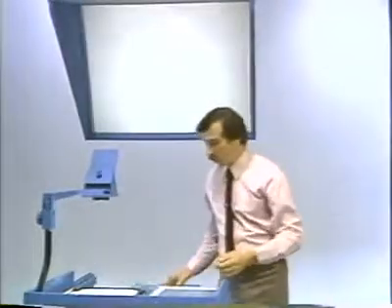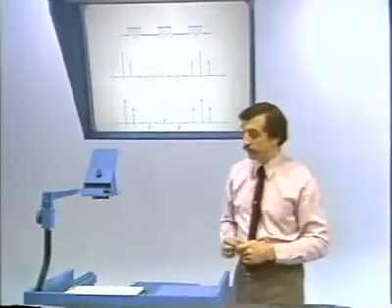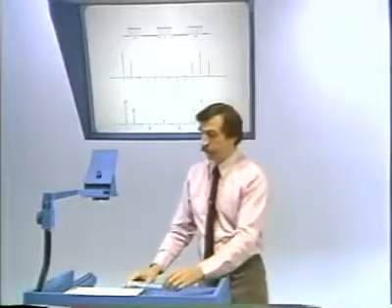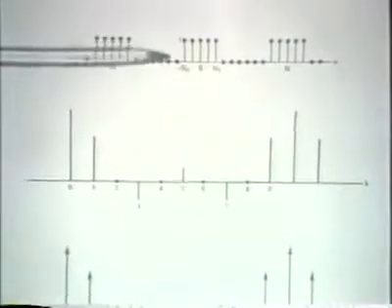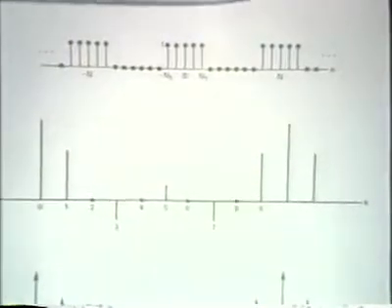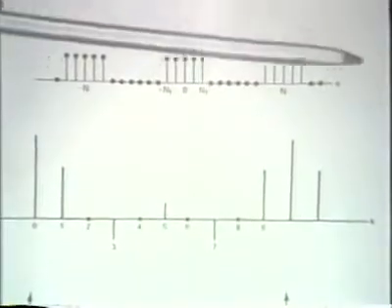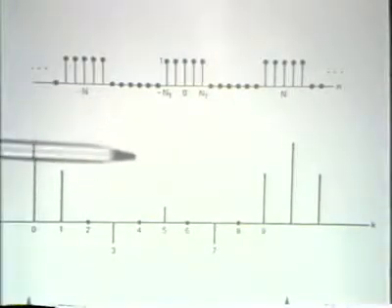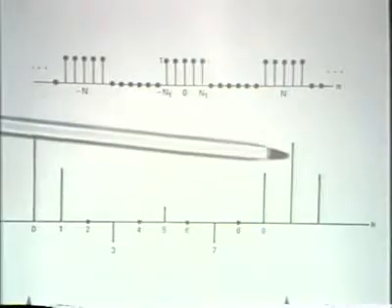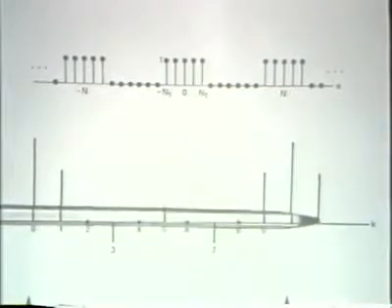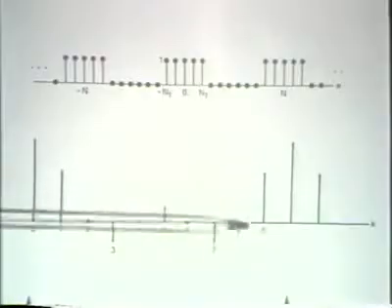So once more, returning to our example, the square wave example that we've carried through this lecture, we can see that really what we're talking about is a notational change. Here is the periodic signal, and below it are the Fourier series coefficients, where I've removed the envelope function and just indicate the amplitudes of the coefficients, indexed on the coefficient number.